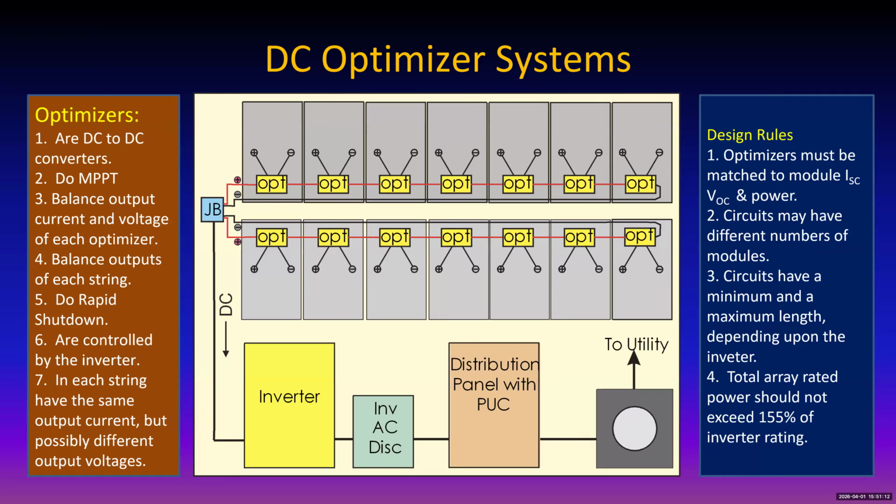But if that just so happens, the inverter has the capability of telling those optimizers, you got to back off and limit the input to my rated power, which might be 7,500 watts, might be 11,000, but whatever the rated power of the inverter, maybe it's 33,000, who knows, it's for a bigger system. So the inverter talks to the optimizers, make sure they don't give it more than it's capable of handling. It's just that straightforward.